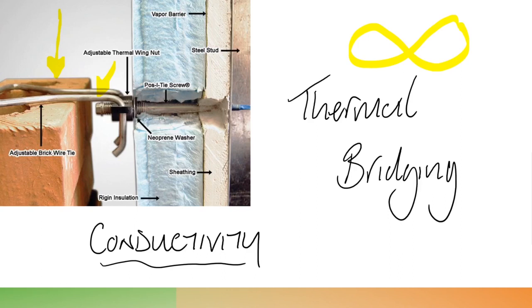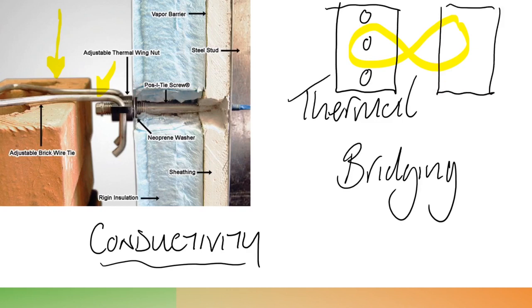Effectively, what you would have in the old style bricks is that you would lay a brick like that, put the holes in like that, and then you would lay a block on the internal like that, and then you would put mortar over, let's use green. So mortar is applied onto each block and the brick, and then another brick and block. In other words, the tie is trapped in between the two, tying the wall together. So that's what the brick tie does.